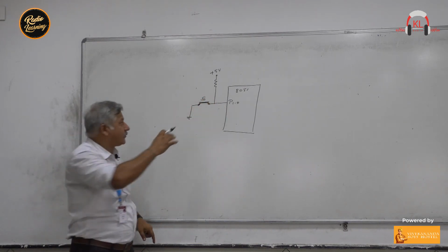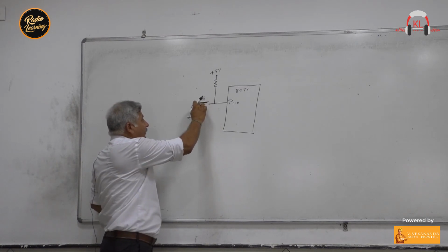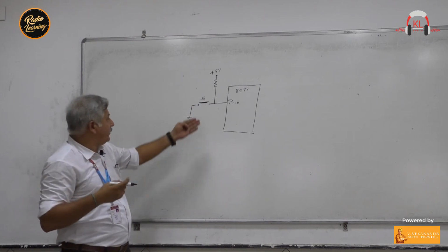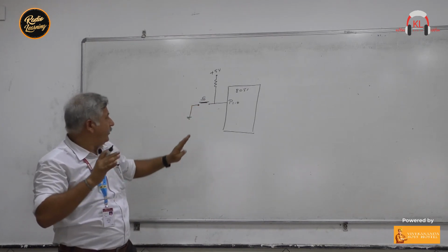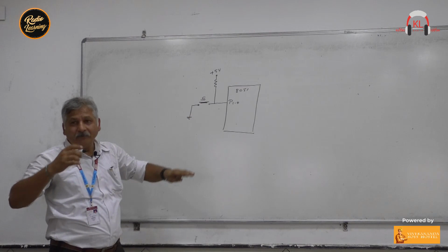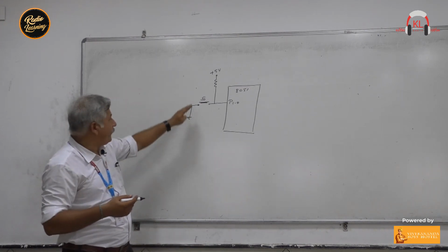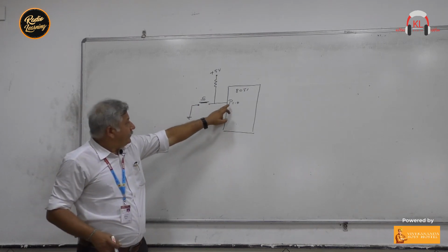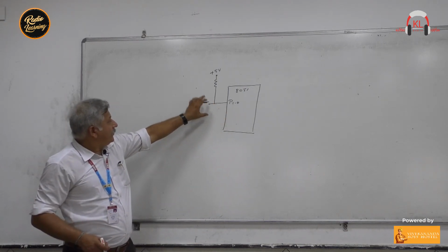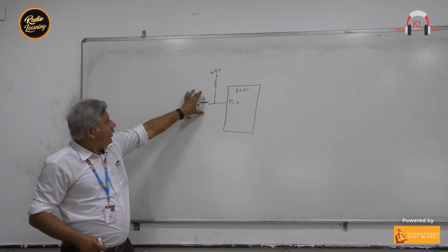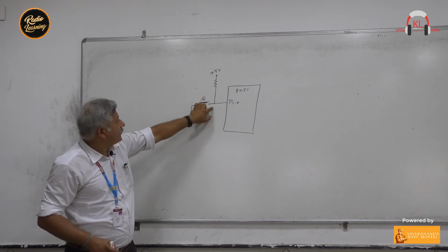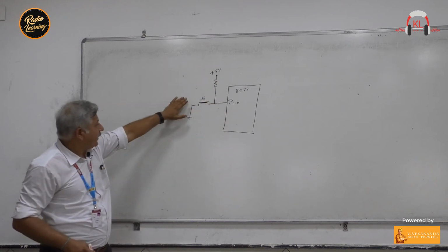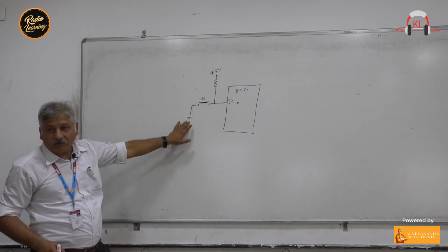And when we release the switch, then this metal, which was earlier in contact with this metal line, will come out. So now it is open circuit. When we are not pressing the switch, the circuit is in open circuit mode, and when we press the switch, it is short circuit. So now this switch is connected between these two pins. This end of the switch I have connected to plus 5 volt through one resistance. The second end of this switch I have connected to ground.